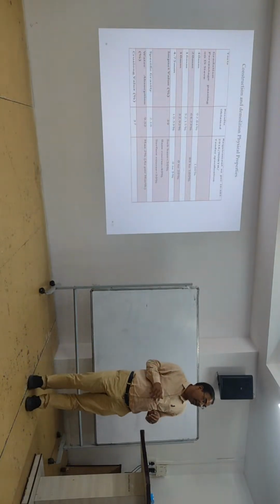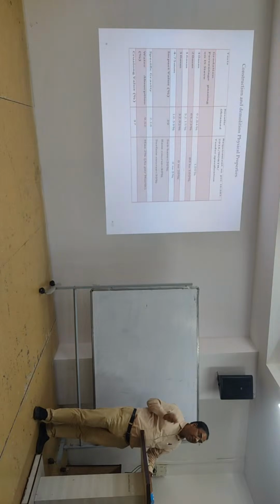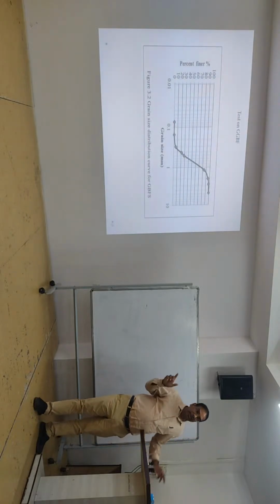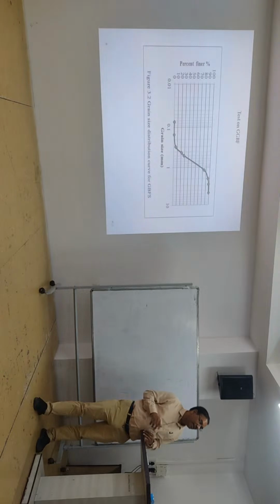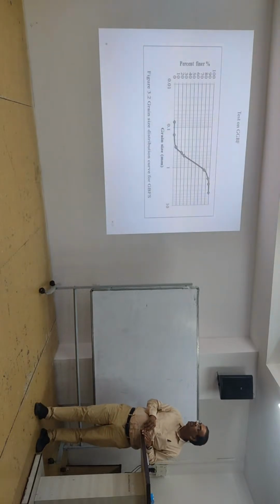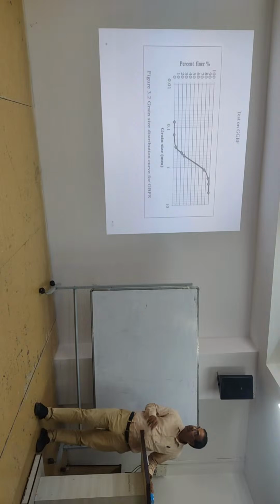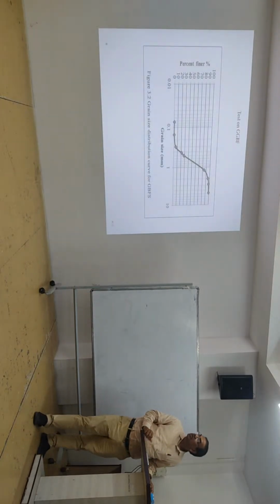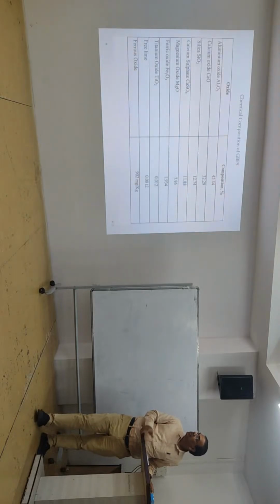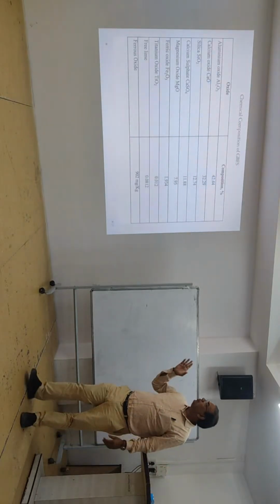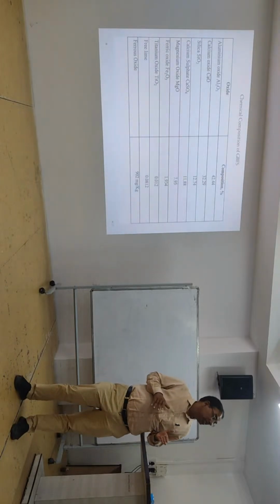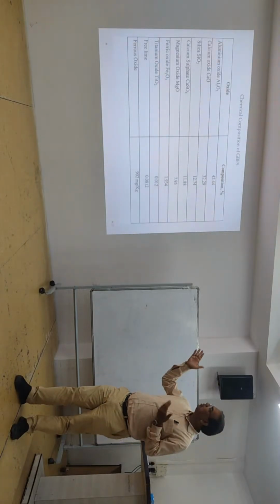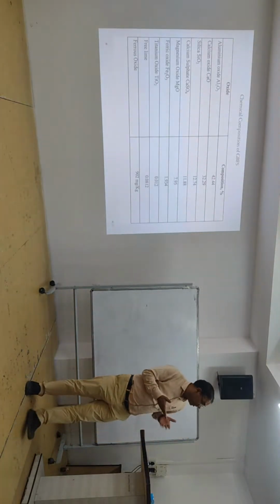Water resistance is very high because of your brick is there. And other materials, cement, in case of lime also we have used this GGBS. That is one of the waste materials from the steel factory. Okay, so this is also waste of the steel factory. So here you can see alumina is there, 42% calcium oxide. So this is pozzolanic material. So this is pozzolanic material we use for stabilization.